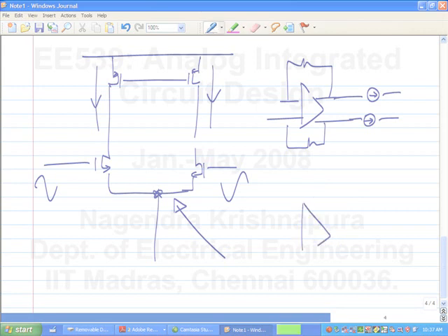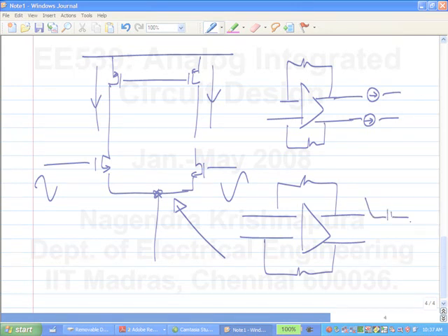So let's say I have some amplifier and I have some load capacitance that gets switched into both the outputs. Now the following circuit will also be fully differential, so it is symmetric about this line. But maybe the two capacitors were charged to zero, now you have to charge them to some voltage. So that will induce a common mode step as well. How fast does it recover from that? Those kinds of things decide. So that is more or less decided by simulation. You need to know which way to go. That's the bottom line.